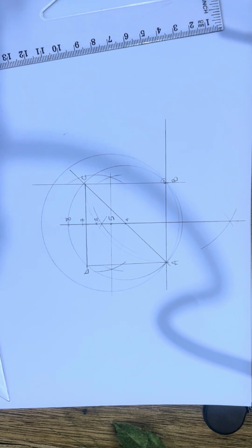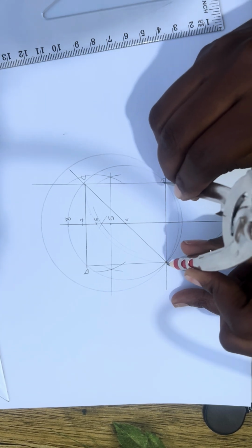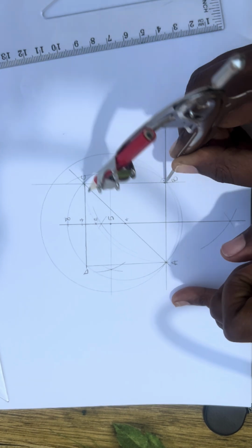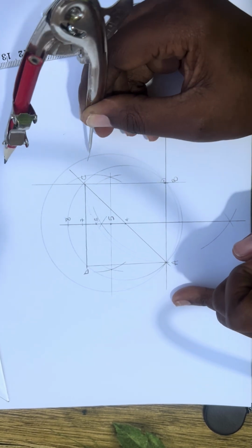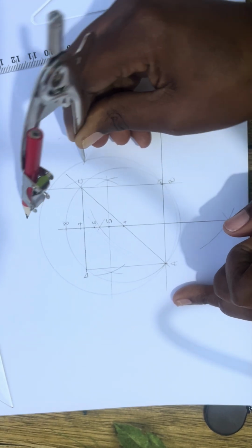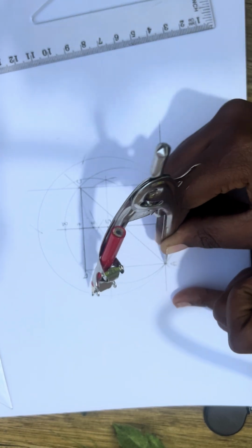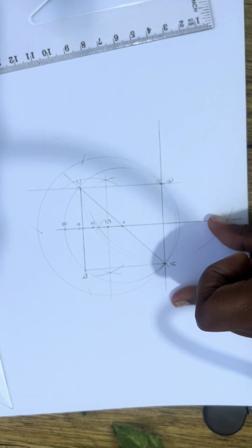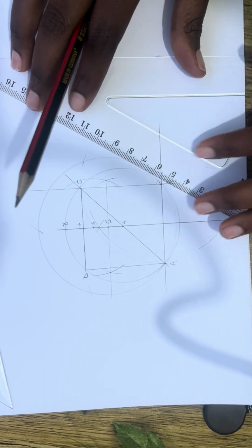Okay, so you come to the point B, take the distance to A, because the pentagon has to have the same sides. Come and hatch it on the circle that you drew. Remember, it has to have 5 sides, so come and hatch it there, and there. So when you join those arcs around the circle, you're going to come up with your pentagon.